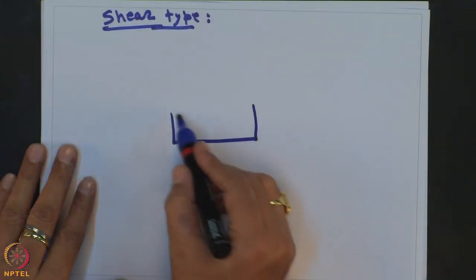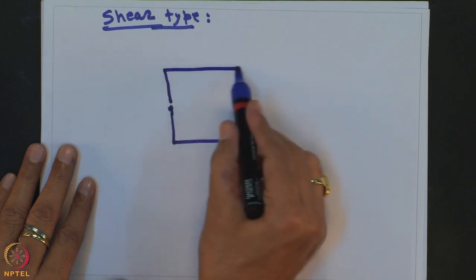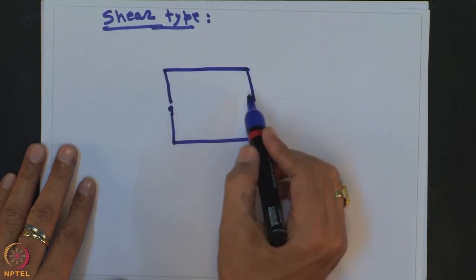So, the resulting geotextile to soil shear strength parameter can be determined. For example, say you wanted to perform a test on the geotextile interface between the soil and the geotextile material. You know what a direct shear test is. So, let us say this is the direct shear test, this is the lower part and this is the upper part.